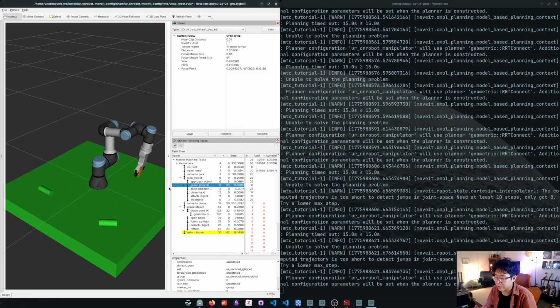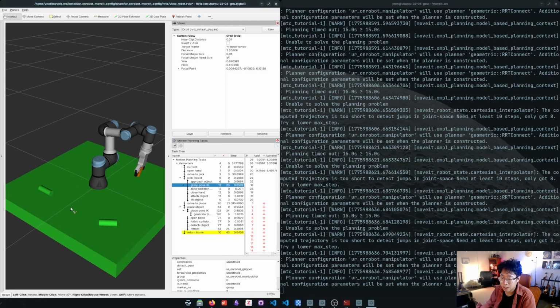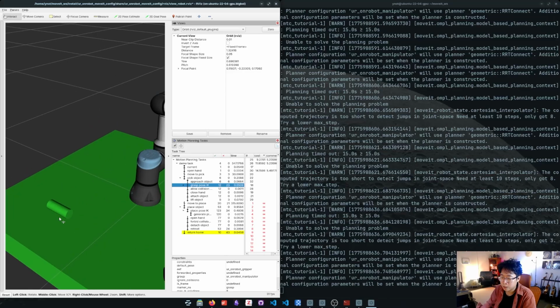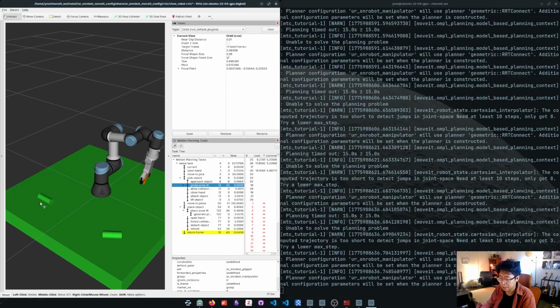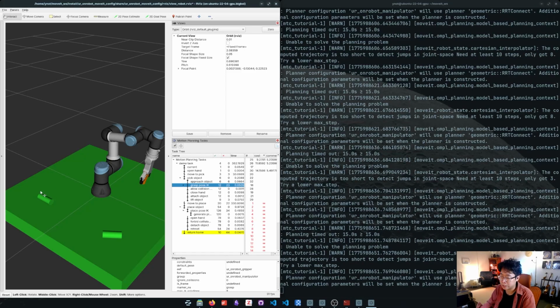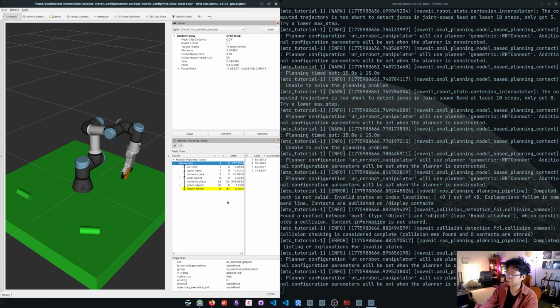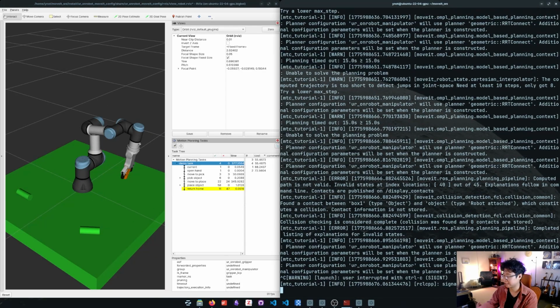The way that we're generating the grasp poses by rotating around the z-axis might not be the best way. With a cylinder, what we can also do is generate more grasp poses along this z-axis, or maybe compute at higher resolution. Like instead of 15 degrees at a time, we can do it at like 5 degrees at a time, for example. So let's implement those changes and try this one last time.